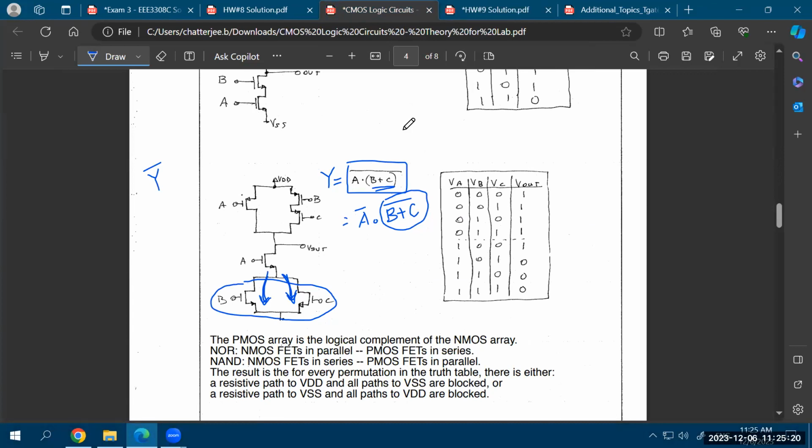So again, as we part for this semester, whenever you are looking at any circuit, maybe the circuit is very complex, but try to think of it in terms of what you already know. You'll see that many times the divide and conquer based approach works best. You just divide in terms of what you already know, that, okay, I see a common source amplifier somewhere. I see a common gate amplifier somewhere. And then try to think of them in terms of black boxes, how those common source black box is connected to the common gate black box, how you have a source follower somewhere connected, and things like that.